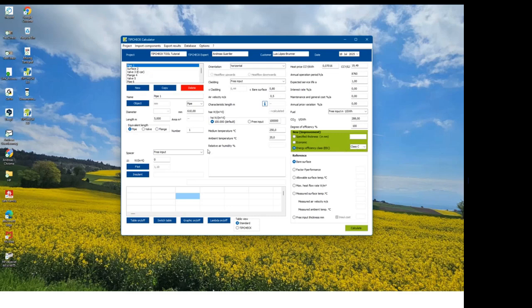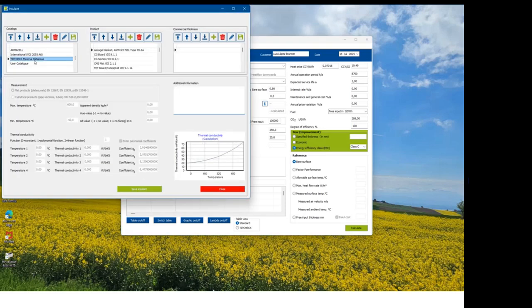All you need to do is check what kind of installation solution you design, or want to propose to your client. For this, let's say we take a pipe section, so we don't need a support structure. That is by default. We take the standard default F value and we go into our database and we check for this temperature for a mineral wool pipe section. So let's take this one.